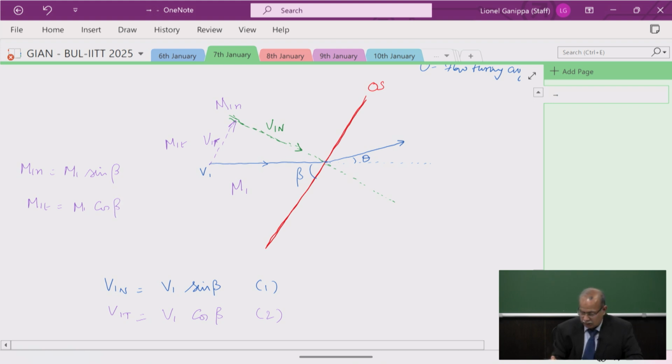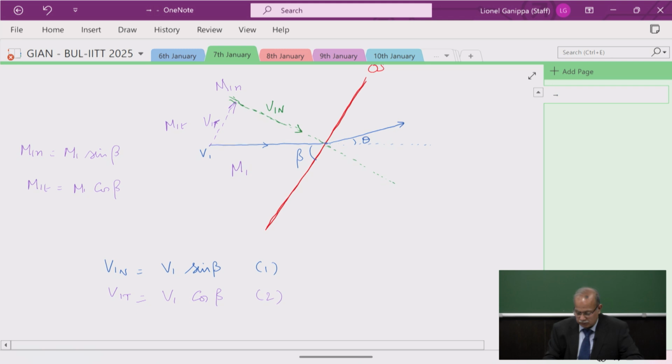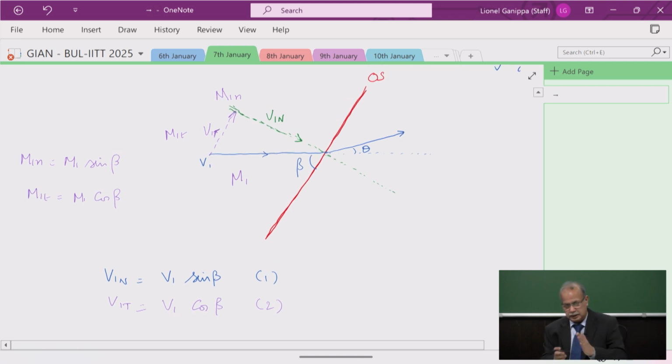This is from the intake side, the flow encountering the oblique shock. Now the flow that leaves the oblique shock will not go straight exactly, but it will be bent. It also has its own normal component as well as its tangential component.